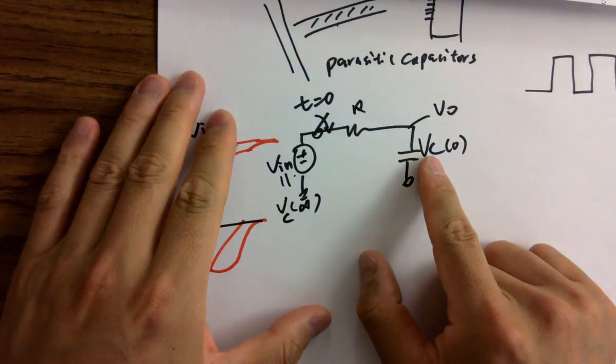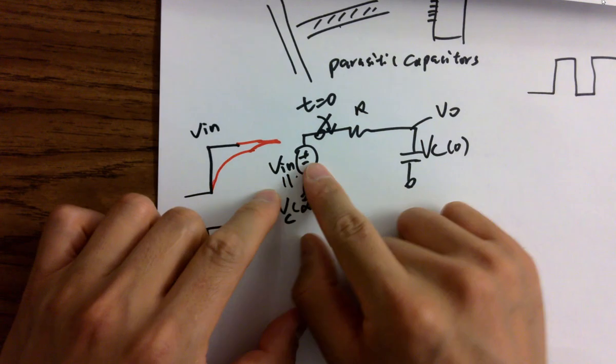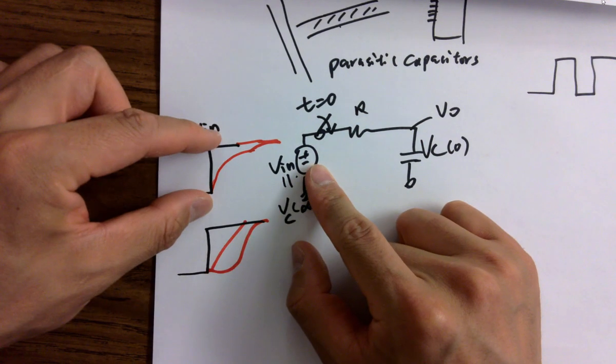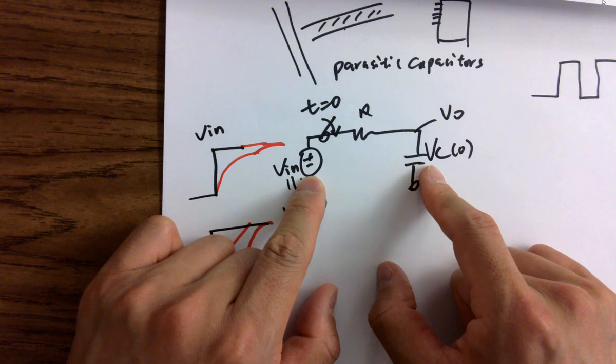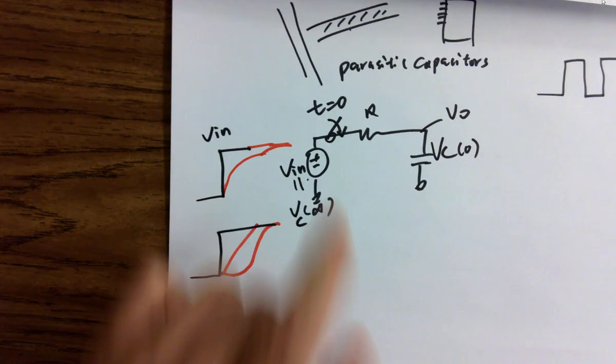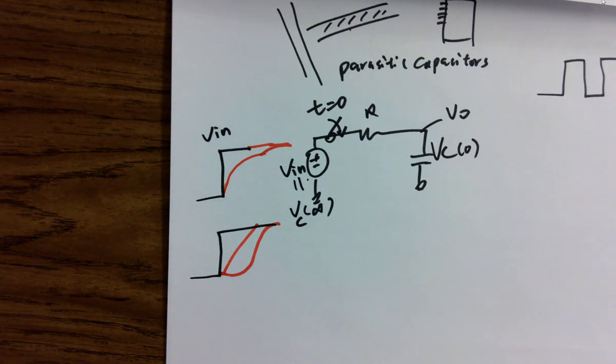One more question. So, for example, this is a 5 volts step. Okay? And what if we have 6 volts initially stored in the cap? And we close the switch, what's going to happen? Yeah, current will go to the left, right? Because of the higher voltage. And then what? After that, current will switch back. It'll go until your cap reaches 5 volts, or once they're equal. Yeah, once it's equal, there won't be any current flowing.